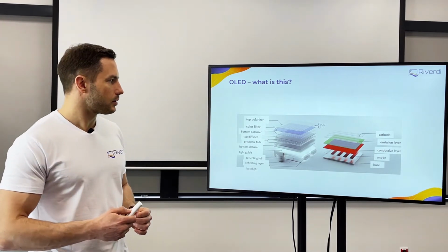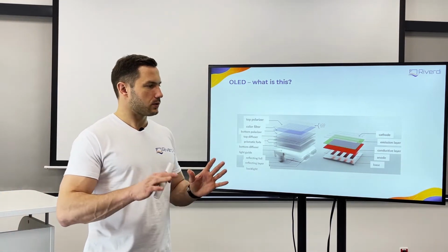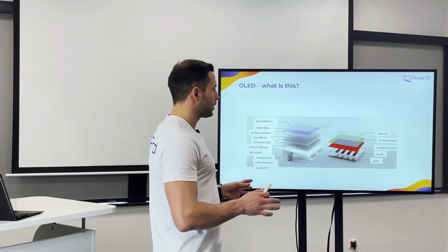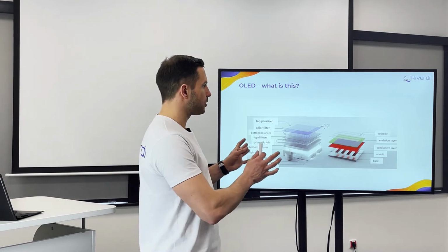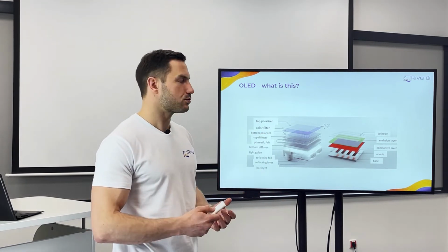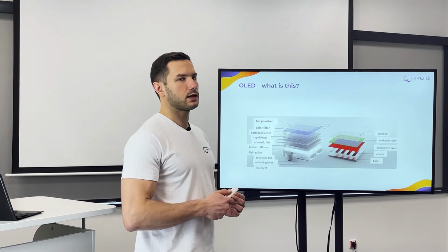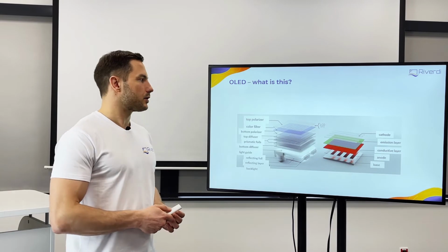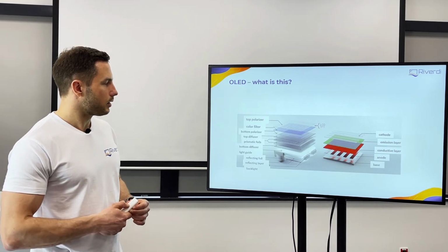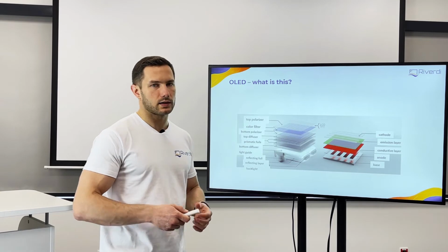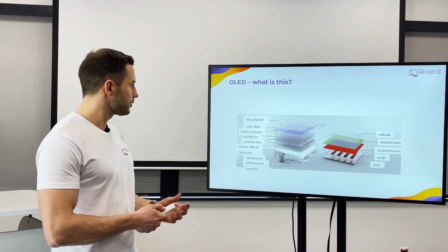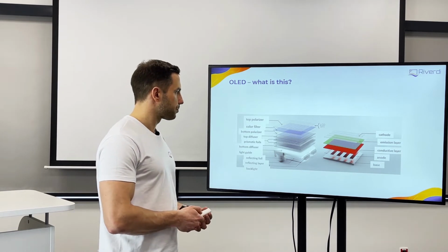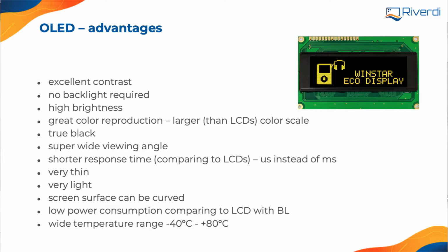It's, I would say, even an unnatural thing to see. Usually the companies use specially prepared movies, let's say a cosmos with the sun in the middle, and the background is black, truly black. It's worth seeing, it's different than a TFT. If you have a TFT next to the OLED display, you will notice that the contrast in OLED is way higher, because there is no backlight and no issue with light going through the TFT always. Yes, a little, but always. So that's the main difference.